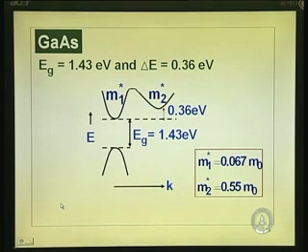If you plot it in the conduction band, it is like this for gallium arsenide. Now, in the valence band, energy versus momentum is like this. I have discussed this when we discussed the direct band gap and indirect band gap material, the difference between gallium arsenide and silicon.